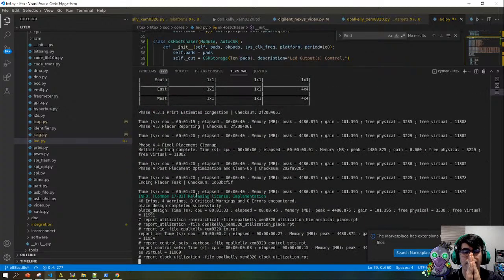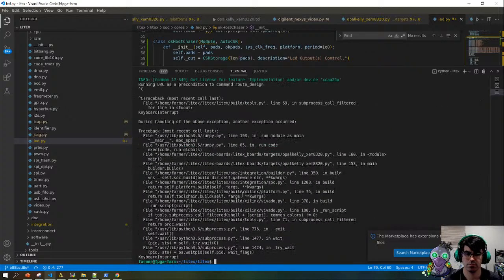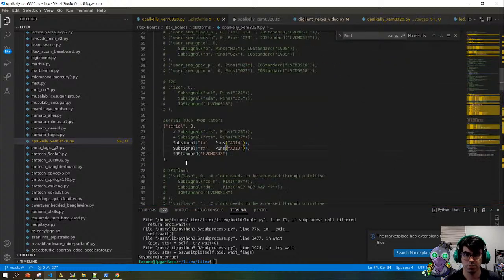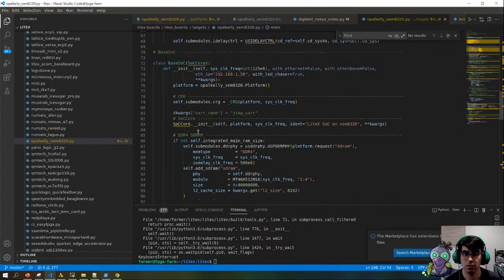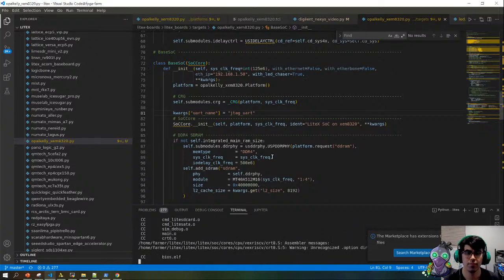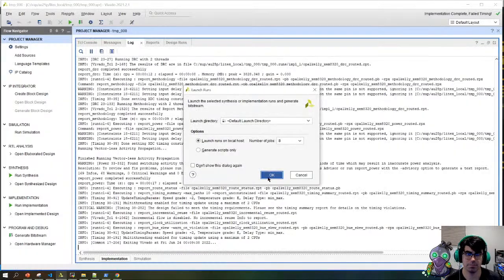Oh, look at it go. Since we're already building it in one location, let's... I want to get the JTAG file working. So be gone. Go over here with my JTAG file. Come back. And now build. You work on that. I go here and generate bitstream.